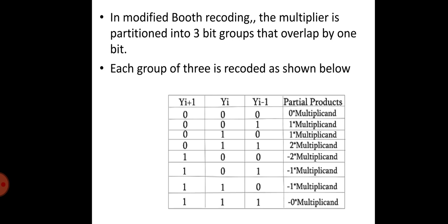One can substantially reduce the number of non-zeros by recoding this number as 2 power 7 plus 2 power 6 plus 2 power 5 plus 2 power 3 plus 2 power 2 into a different format, and you can verify the form of it is 1 0 0 0 0 1 0 with a 1 bar, where the shorter notation is minus 1, which represents the same number.